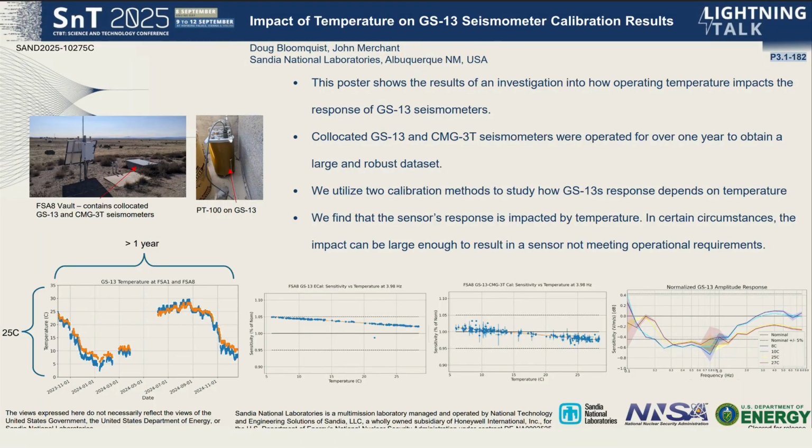And I also have the next one, still John Merchant, but this is the work of my colleague, Doug Bloomquist, who could not be here. We've also been investigating the effects of temperature on seismometer performance. So we have a year-long study in which we placed thermal probes on seismometers, continually measured their variability in electrical calibration and frequency response, and correlated those changes to show that seismometers have measurable temperature effects that can also push their performance outside of the operational requirements. So again, if you'd like to hear more about this, the poster is number 24, right next to number 23, so I will be there for both. Thank you.